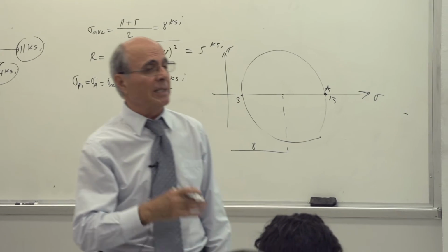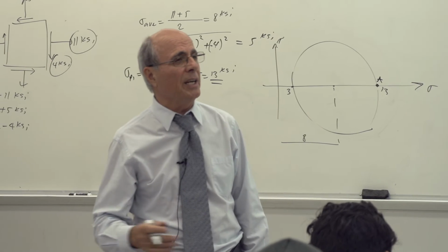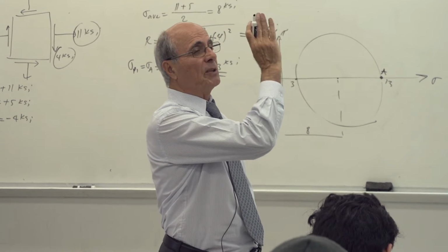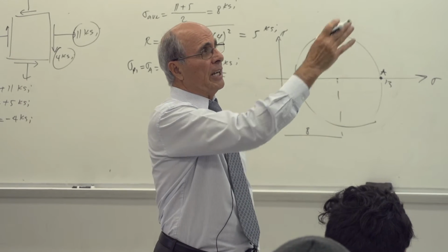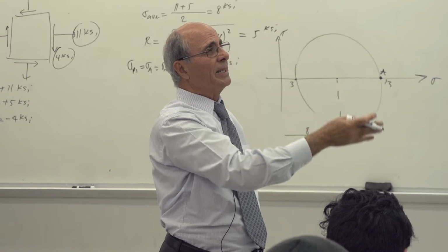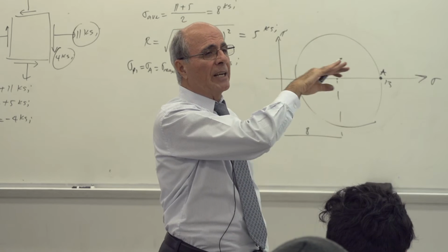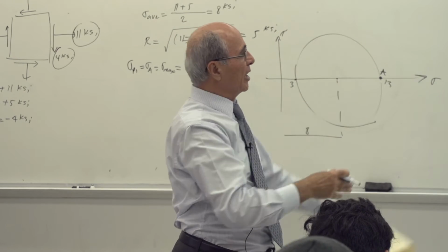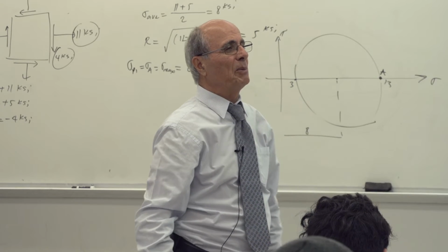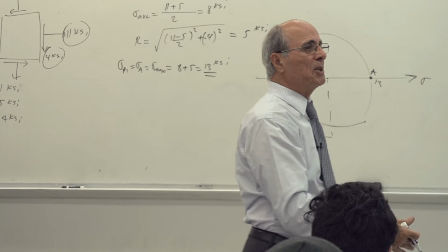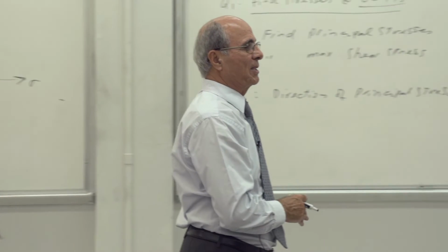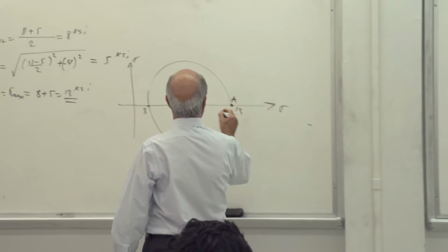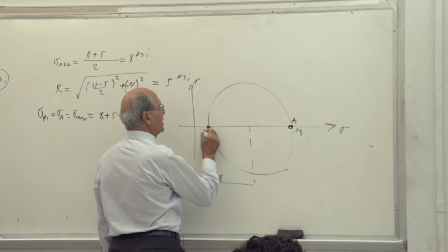So you appreciate that every design has to go through the Mohr Circle, because the stresses are not maximum on the vertical. You never find any surface like that, which is a plate, cracks vertically, and it may, but that's for a different reason. Usually the crack is along the theta P and theta S. Everybody see what I'm talking about, where the shear is maximum and where the normal stress is maximum? Everybody getting the idea there? So these are the points you want to put in your design. So it happens there, in every design.